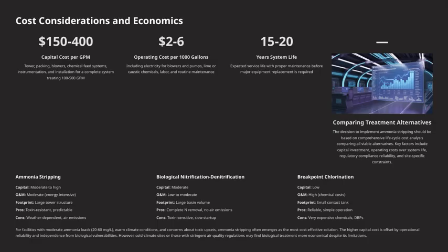Biological nitrification denitrification has moderate capital costs and low to moderate operating costs. It needs a large basin volume, but offers complete nitrogen removal without air emissions. The downside is that it's sensitive to toxins and has a slower startup time.